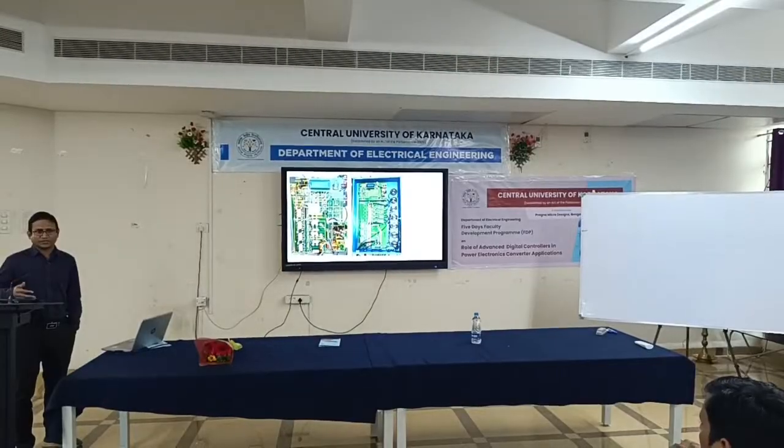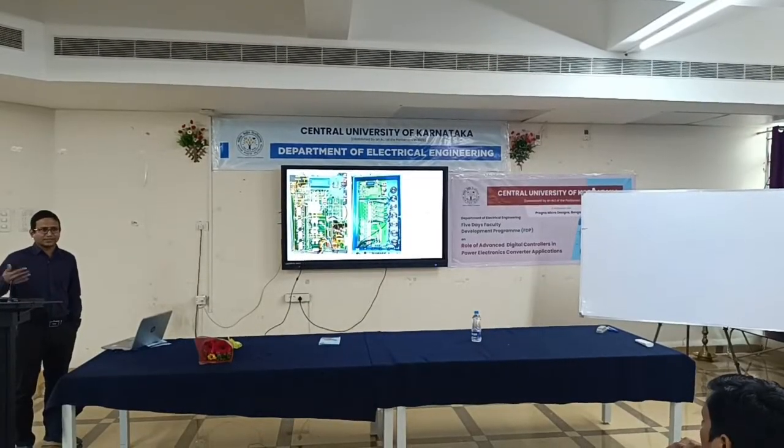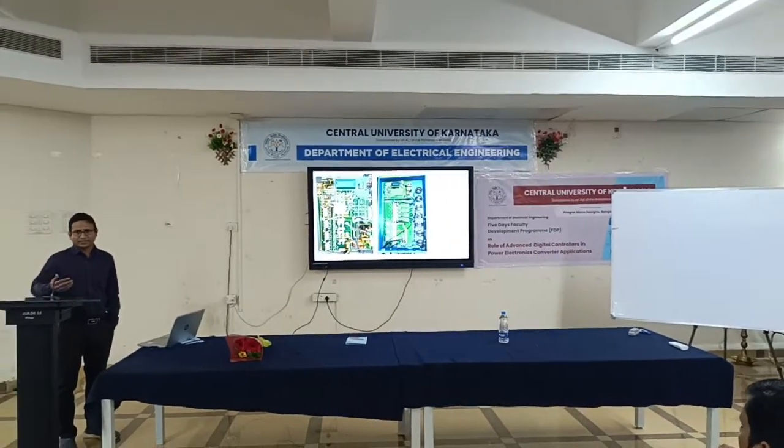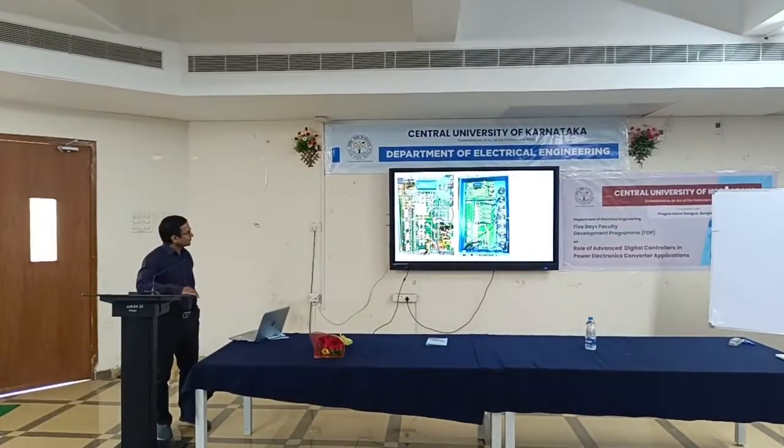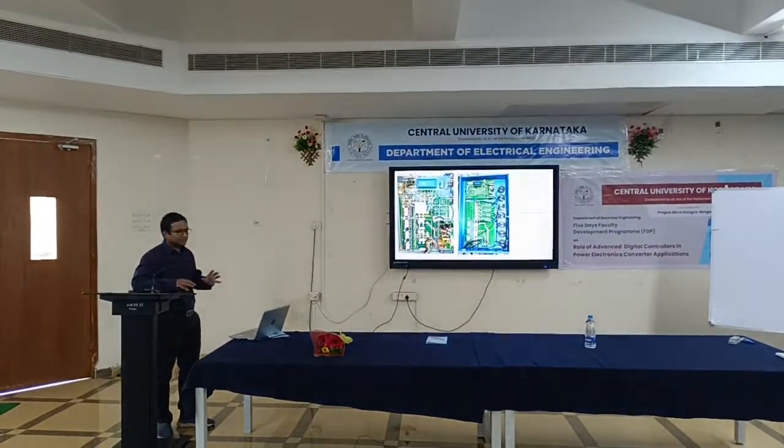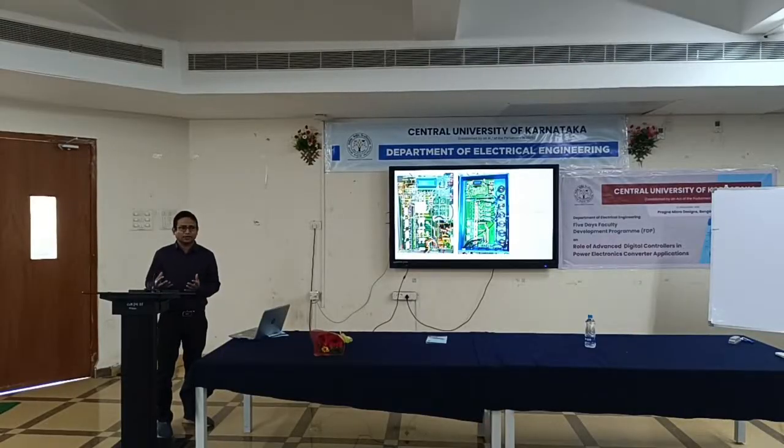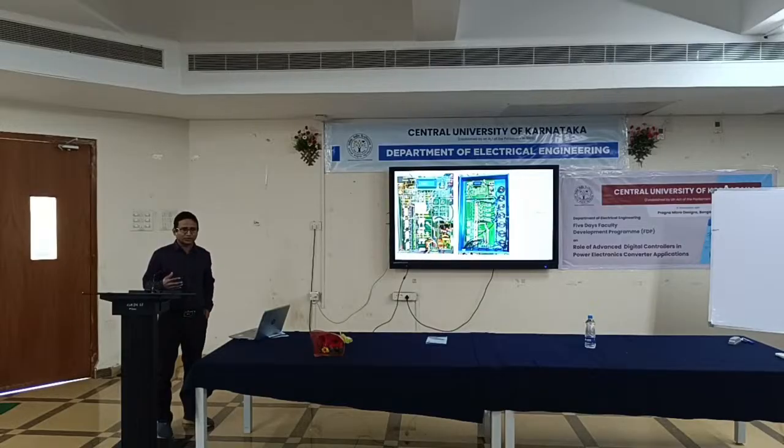Many of you are MTech students, PhD students, and there are my respected faculty members. We do all our research in developing the control strategy. We model the power converter. Then we develop the control strategy like inner current control loop, outer voltage control loop. We use PI compensators, we use filters, and so on. We used to use analog based control.